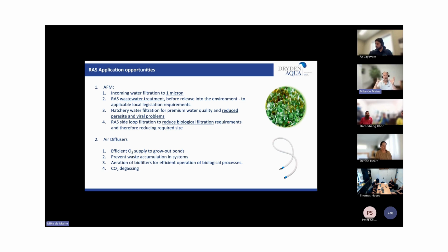So your bacterial regime is moved towards the heterotrophs rather than the autotrophs, which the autotrophs is what you want to convert your ammonia to nitrates. You don't want so many heterotrophs in your system converting the organics to ammonia first, then to the autotrophs to get to nitrates, because that just needs a much larger biological surface area, right?